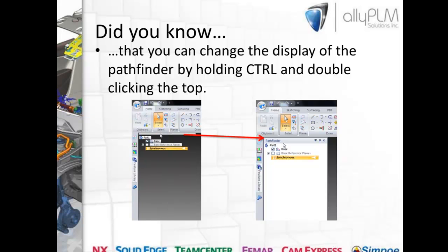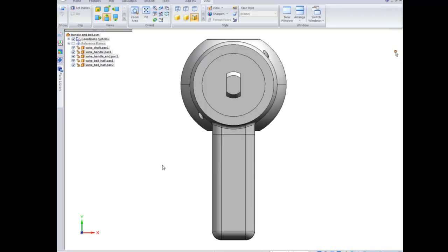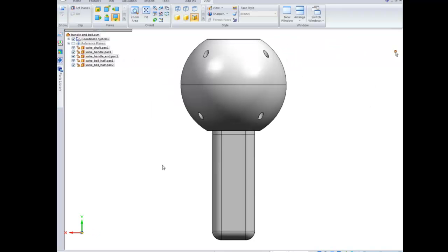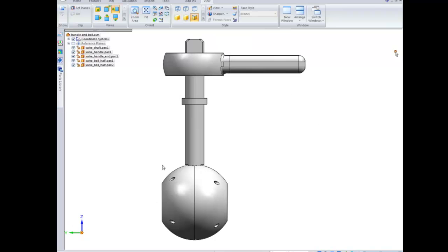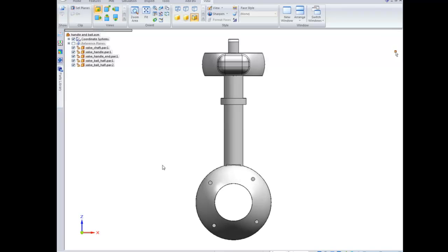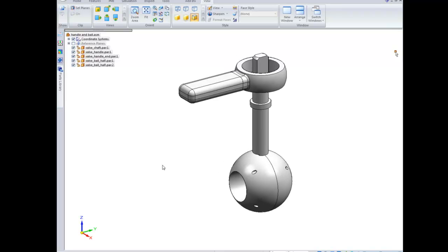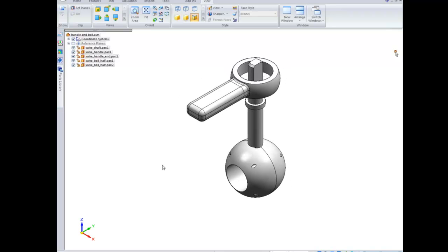So if we go to Solid Edge, I can show you this. First, I'll show you those model views. So if we do Control-T, we can get the top view. It fits it for us. B does bottom, excuse me. L is left view. R is right view. And we've got F for front and K for back. Then we also have our isometric, dimetric, and trimetric. So those are all the keyboard shortcuts for that.